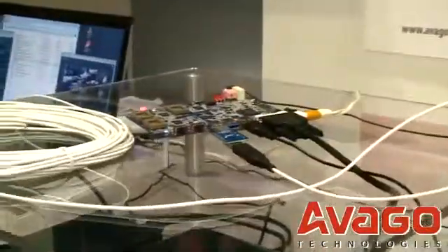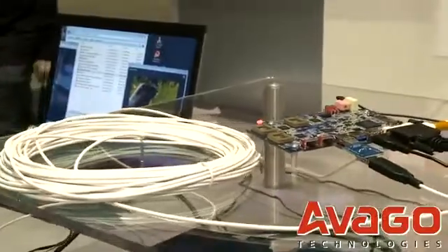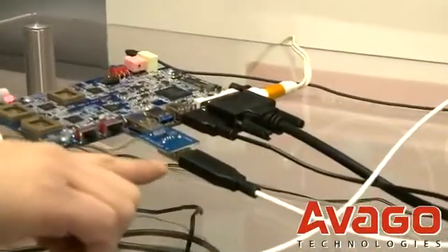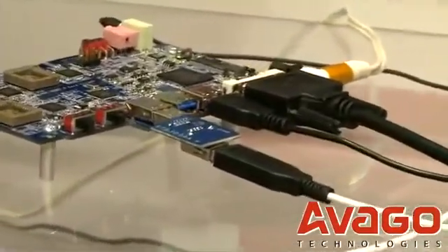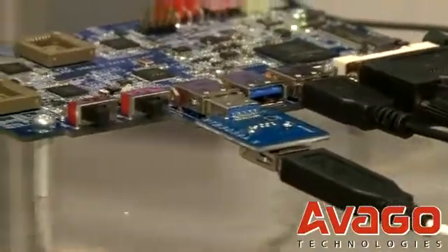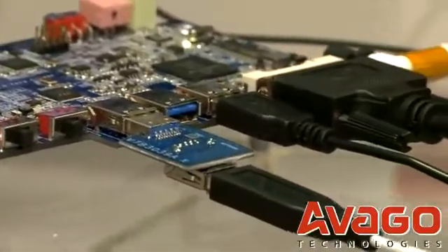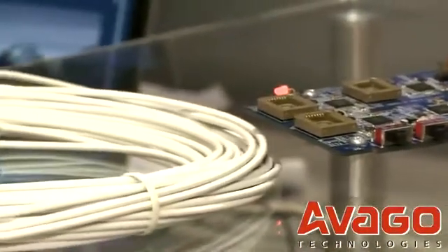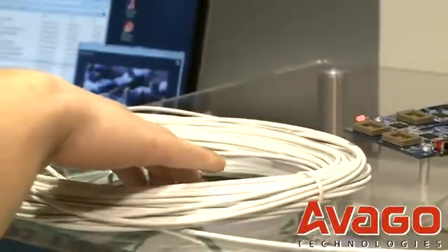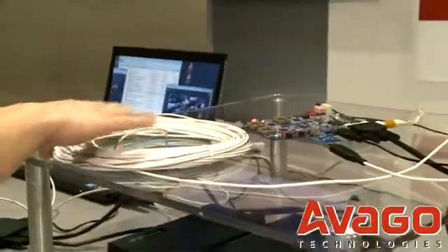In this Avago Technologies USB 3 active optical cable, the active components are integrated into the cable. In this section right here is a PCB, the Avago Technologies 850 nanometer VCSEL and PIN, as well as a highly integrated IC for laser driving, receiver circuitry, and digital functions. This USB 3 active optical cable has a maximum link distance of 100 meters at 5 gigabits per second. So it's able to surpass the limitations of copper interconnects, and you're able to go 100 meters at 5 gigabits per second while still maintaining the low cost and low power typically seen in consumer markets.